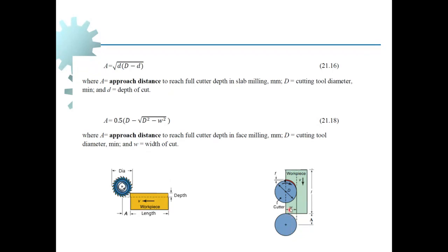So we are just taking the cut from a portion of the top face and not the whole top face. So the value of D is this much. And then the diameter is another parameter which plays a role in what the value of A is. So depending on the type of operation, either face milling or peripheral or slab milling, we have to make use of the right equation to get the value of the allowance computed.